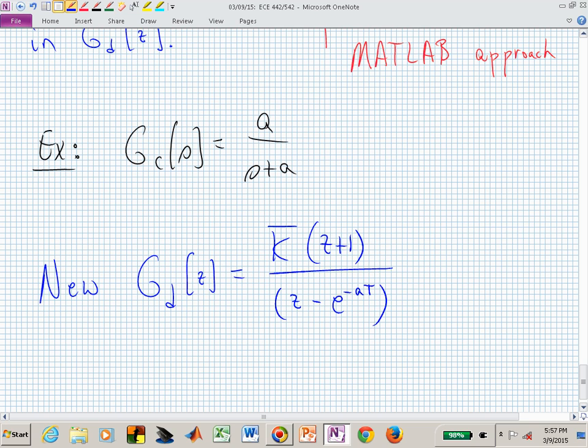Now what we want to do is we actually want to eliminate that factor, because we had 1 zero at infinity, and we said let's map 1 minus 1 of those into this factor z plus 1. Now we have a factor z plus 1 raised to the 0th power, or it now gets eliminated. So we're going to remove this factor,